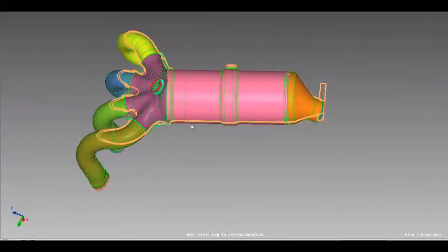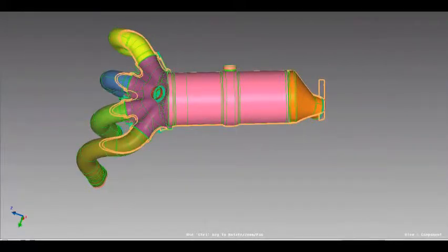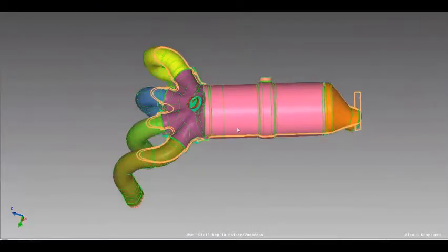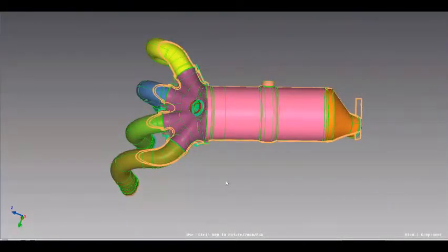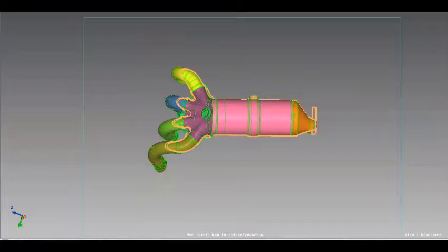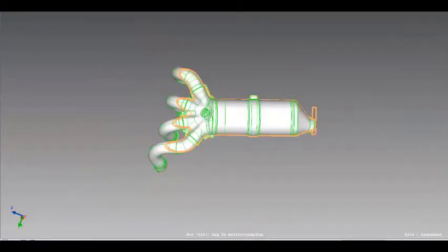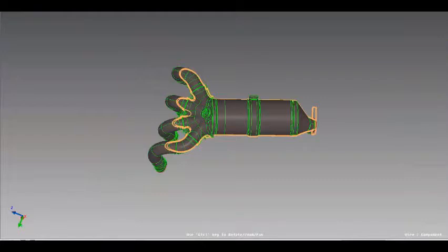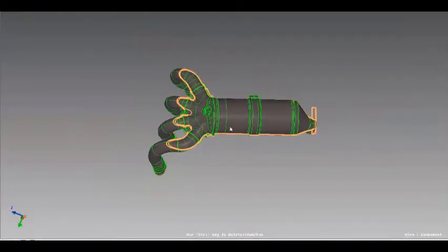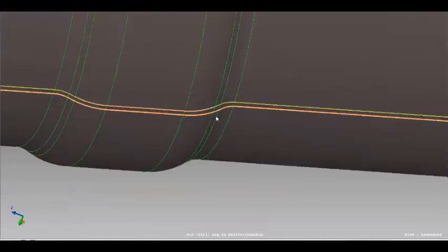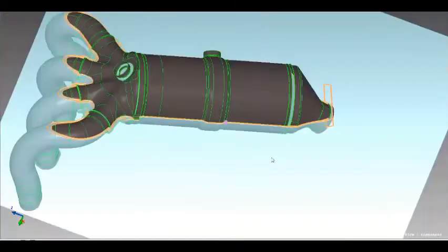So it seems now I have created my wet surfaces. It says 414 wet surfaces have been found. I want to create a section view so that we can clearly see how MeshWorks has generated the wet surfaces. For that I'm going to create a section line, using the intersect method, and I'm selecting all my CAD. I want to define my axis, which is X, and I want to pick the center, which is on the same existing line, and just say create.